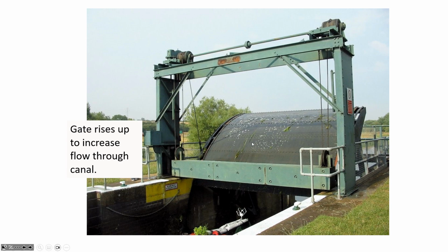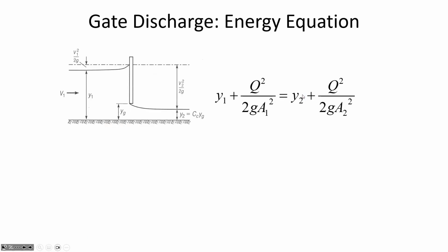But if you have a radial gate like this, since the hydrostatic forces are pushing through a central axis, there isn't the same friction effect. So you'd only need to lift up the weight of the gate rather than also the additional friction forces that are caused by the gate getting smashed closed.